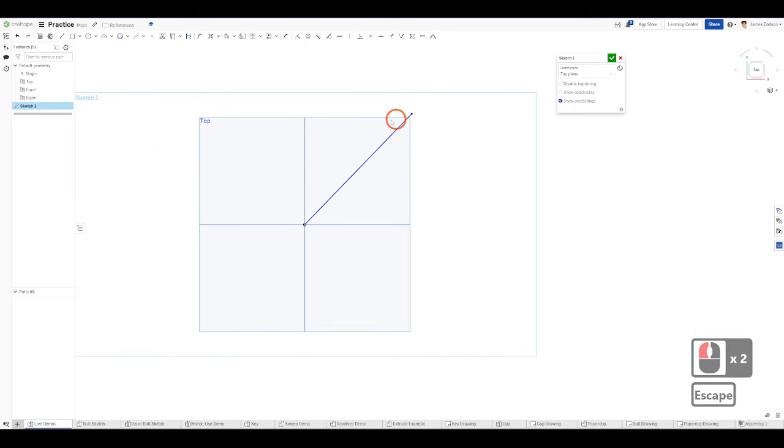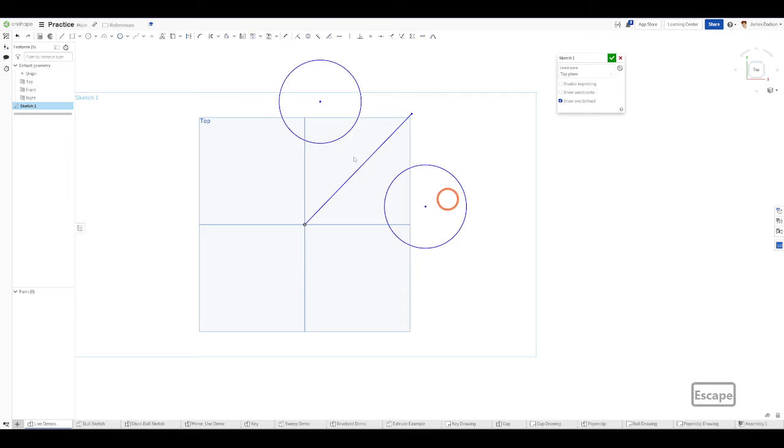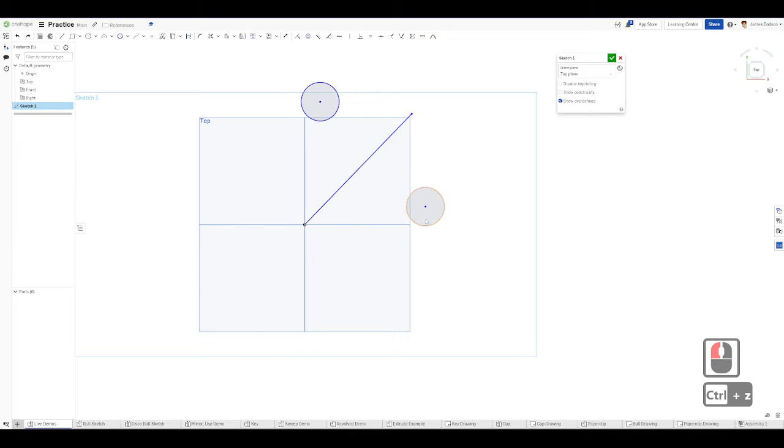And mirroring also works in any direction, right? So if I've got something over here and I want to mirror it, I select my mirror line, select my entity, and now I've got my mirrored thing. Also, you can do things in different orders, and mirror is one of the commands where this works. It doesn't work for everything, so don't try it on everything.